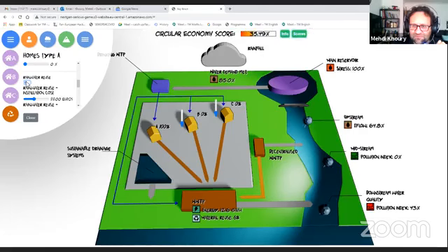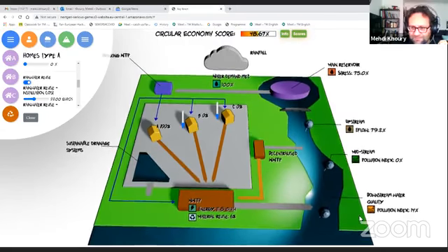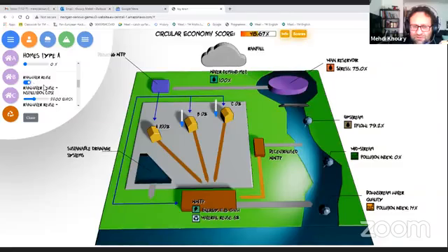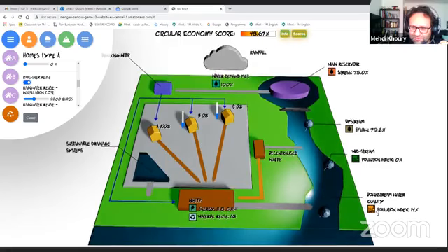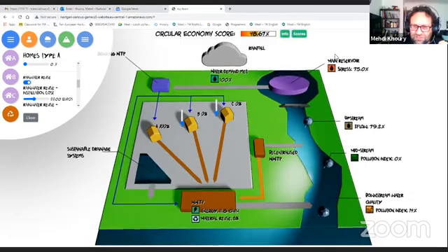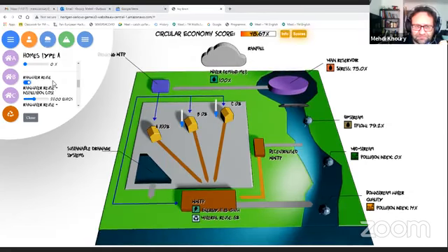So instead of 100%. And if you look down to the right, your pollution index, when you didn't use rainwater reuse, was 43%, and it goes down to 14%. So in a way, rainwater reuse seemed to be a pretty good technology to both minimize pollution in that case and also minimize water stress.